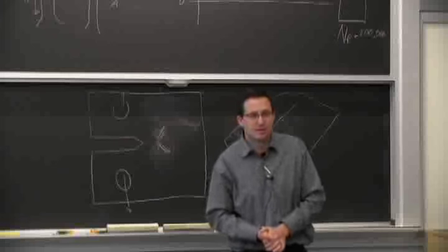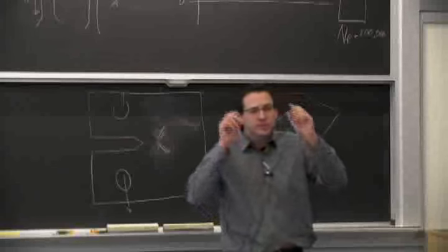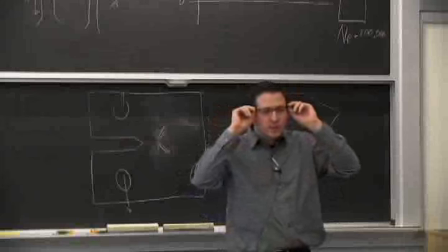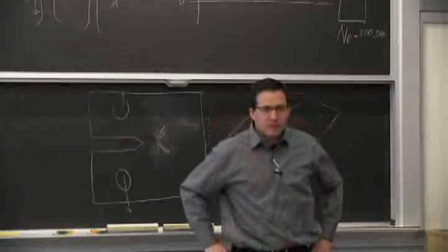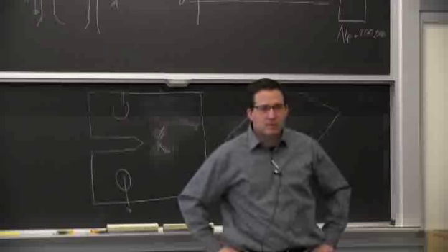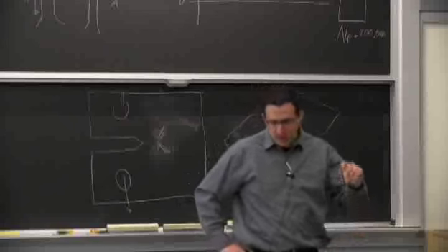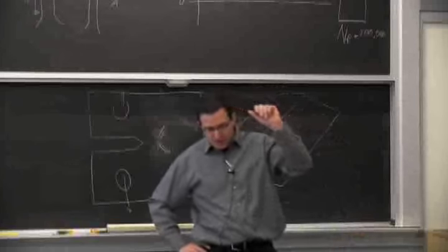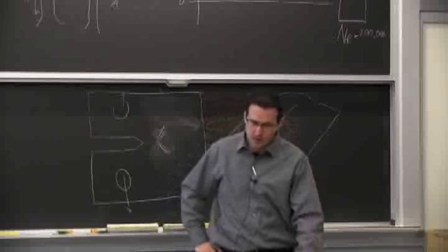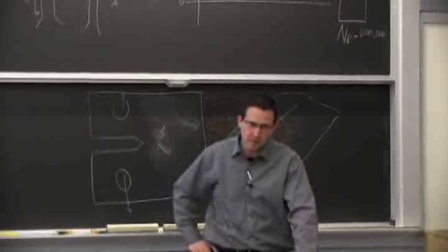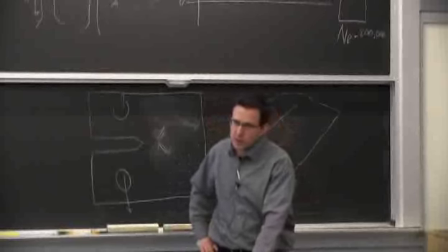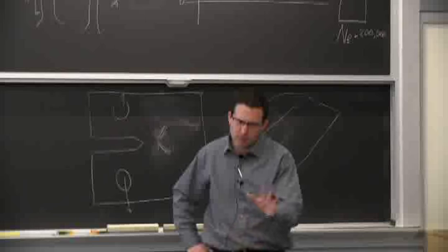Yes? So that basic trade-off between yield strength and fracture toughness, that design decision, I assume, largely comes down to how much confidence you have in what the maximum load is that you'll see, what kind of safety factors you're working with, that sort of thing. Okay. So the question was between using the yield strength or tensile strength as a design criterion, or using the fatigue properties as a design criterion.